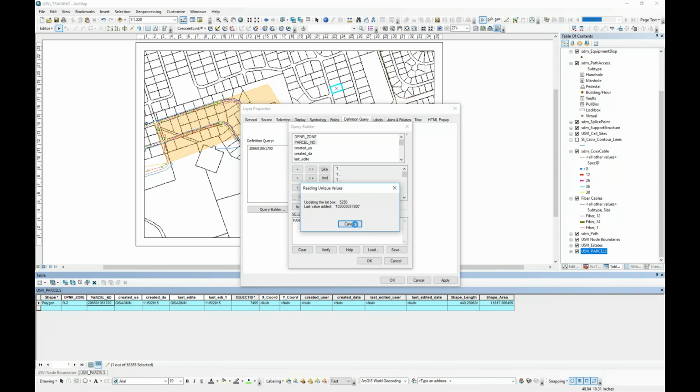Get unique values. That's going to get a lot of them. So you look at 206. You start typing 2066. And sometimes we get so many, it won't show up. If you know exactly what it is, especially being a number, if you put it in with a single quote on each end, you verify it. It's okay. You're looking for just that parcel number. Parcel number equals. You verified that it's correct. It says the expression was successfully verified.